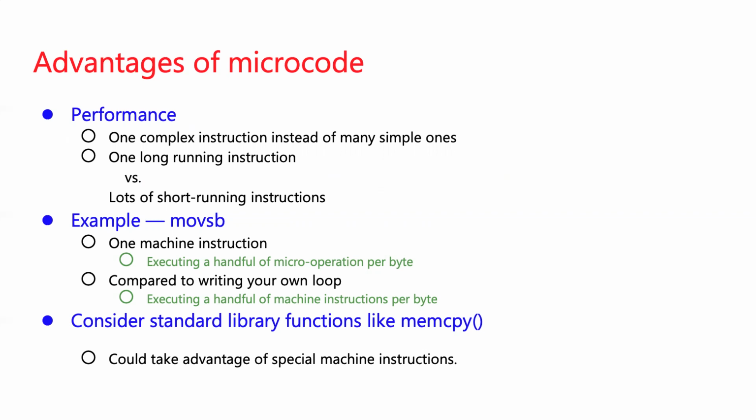In fact, if you look at the 8086 instruction set, you'll see what are called string instructions, where an individual instruction can copy or compare or search for things in a whole sequence of memory locations. And that's what we're going to talk about next. These are kind of like the multiply instructions. They're implemented with the help of microcode, and any one of these instructions could be like running a little program from a single assembly language instruction.